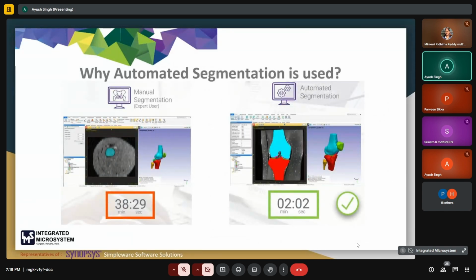To summarize, the AS Ortho module in Simpleware is a dedicated auto-segmentation solution for orthopedic applications. It brings together the power of machine learning, anatomical intelligence, and workflow automation to address the time-consuming nature of traditional segmentation methods. One of the greatest advantages is that users do not require advanced training in imaging software or manual segmentation techniques. The software guides users through a step-by-step process where they can select the anatomical region, import the image, and generate the segmentation with a single click.